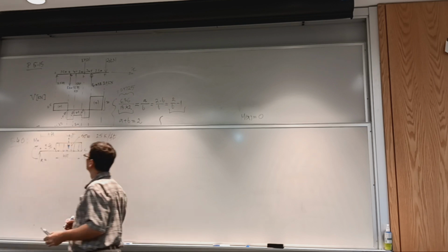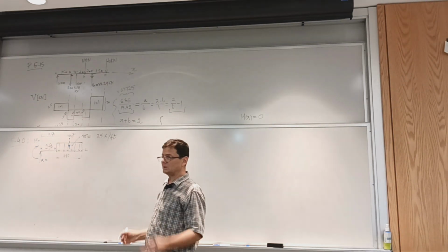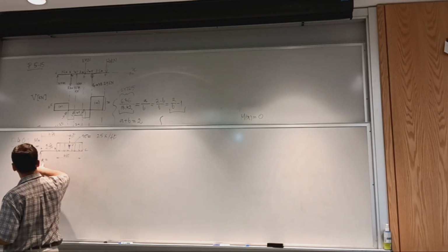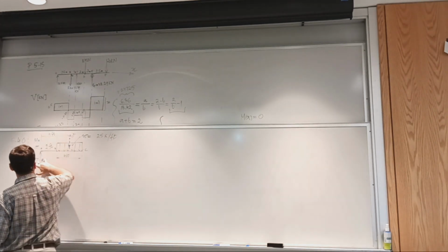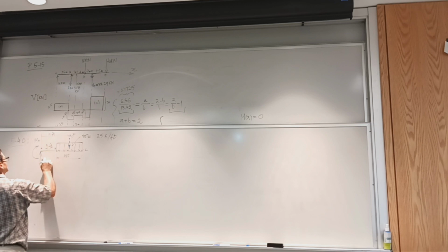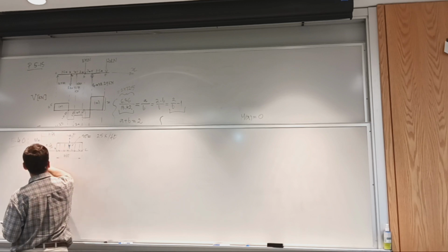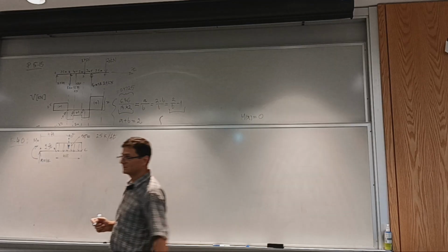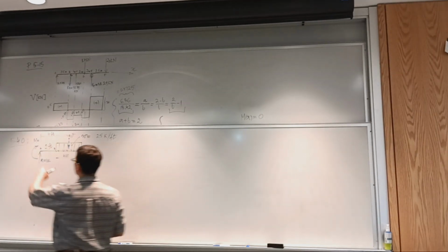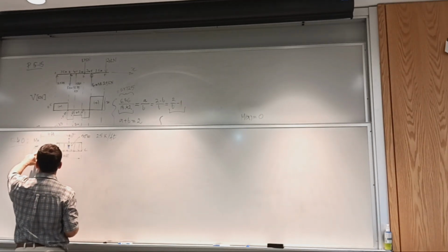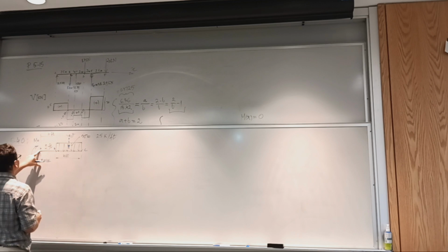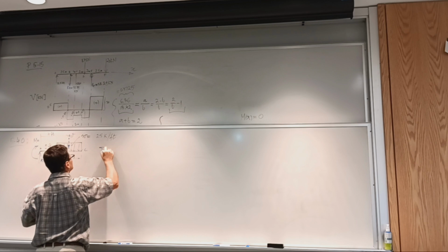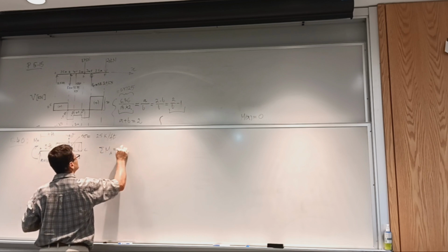10K. All right? Here you don't sum moments about two locations. We use directly the sum of forces to get R, and then sum moments. The sum of forces in the y direction gets us R, and that's going to be 10K. And then for the moment, what's the magnitude of M? You sum moments about point A, where R does not have an arm. So sum of moments about point A equals 0.